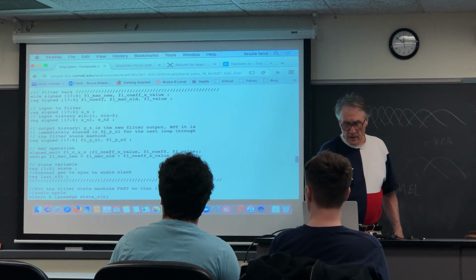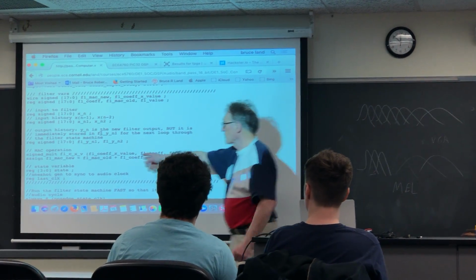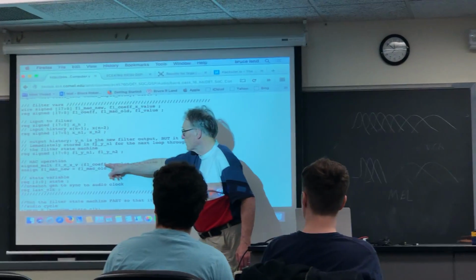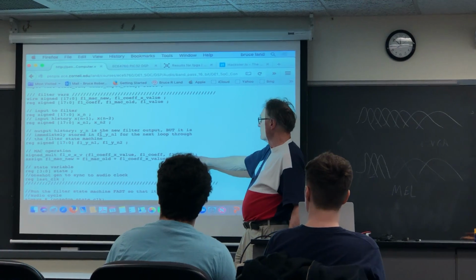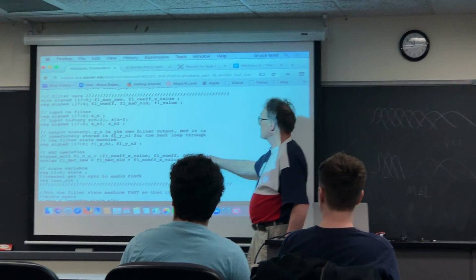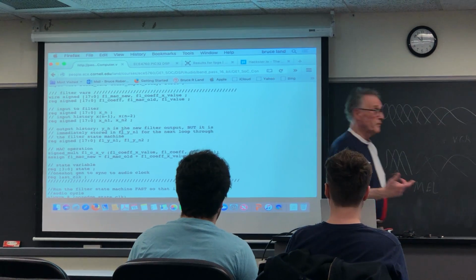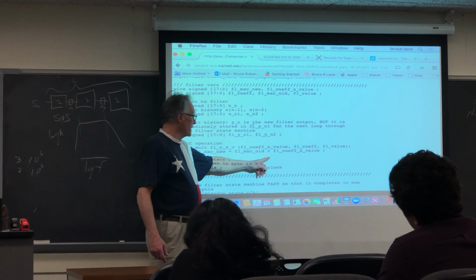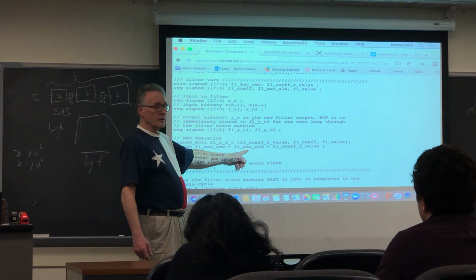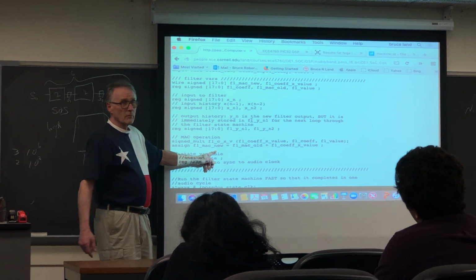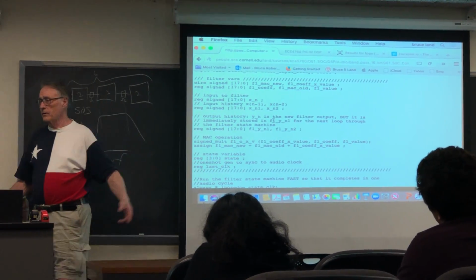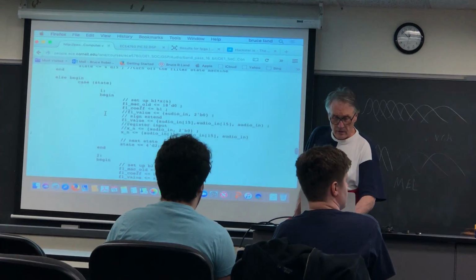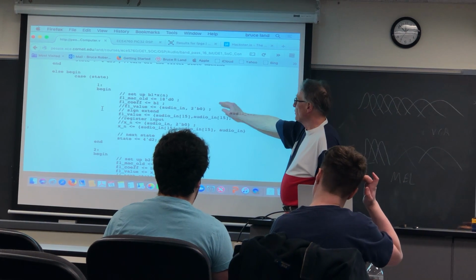And the way it works is to define a MAC operation, a multiply and accumulate operation, which is to use a hardware multiplier block to multiply some coefficient times some value, because it's a linear filter, it's always a coefficient times an input value, and then take this product and add it to the old MAC output to make the new MAC input. So you're doing a running sum effectively of terms. And then you merely step through each term.